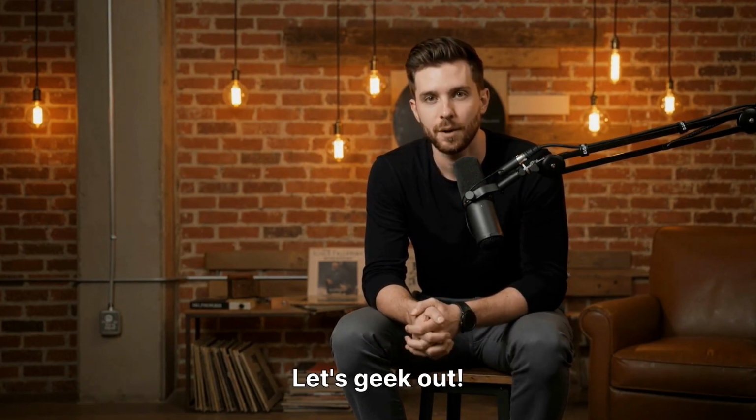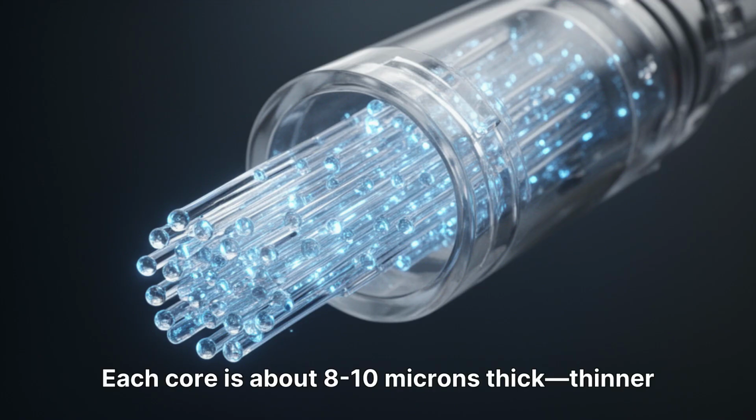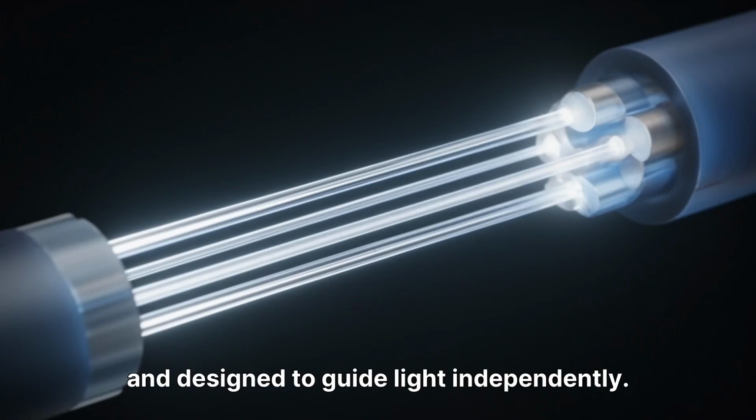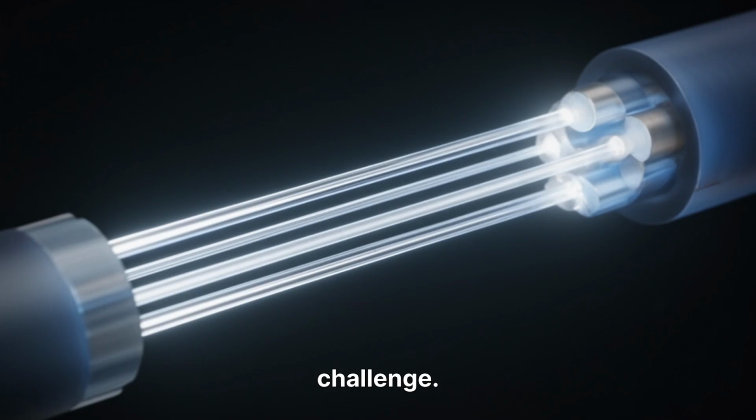Today, we'll explore the engineering magic behind MCF and SDM. Ready? Let's geek out. At its heart, a multi-core fiber is like a bundle of tiny glass rods sharing one outer jacket. Each core is about 8 to 10 microns thick, thinner than a human hair, and designed to guide light independently. But keeping them independent is the real challenge.